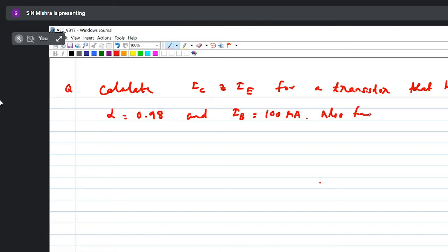So if you are designing an n wavelength multiplexer, you will require n minus 1 fiber Bragg gratings and n minus 1 circulators. Here we have considered 4 wavelengths, so we will require 3 circulators and 3 fiber Bragg gratings for combining and separating these 4 wavelengths.